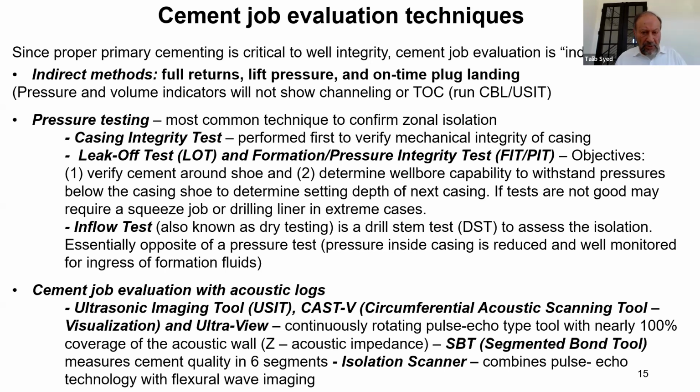Leak-off test and formation pressure integrity test are basically the same, but in one, you carry the pressure increase to the formation fracture point, and in the second, you drill ahead, but not to fracture. But you always got to make this decision before you do the test, whether to carry it to fracture or not. And then finally, don't use info from straight holes for deviated holes and vice versa in the same field.